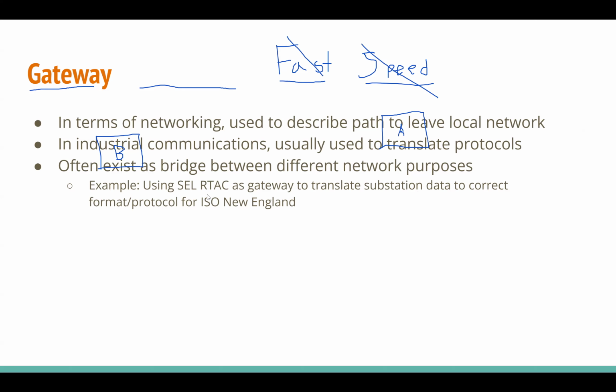For example, something you'll see all the time is that we use SEL real-time automation controllers, where you can do a bunch of programming to do some really cool things. They're very similar to PLCs. We use those to act as the gateway between your substation and your control center, or to ISO New England.